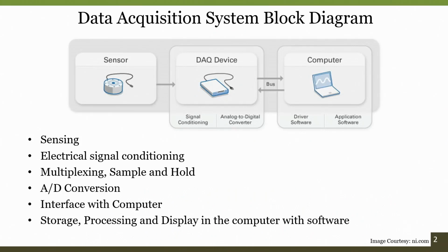So, as I briefly explained, from a complete system point of view, you will always have a sensor that converts your input physical parameter, or physical measurement, into electronic-system-understandable signals. Even in this case, if your input is a biomedical signal, the output will be in the form of an electrical output voltage. So you have an input as well as an output, and that will be connected to a signal conditioning circuit followed by an ADC.